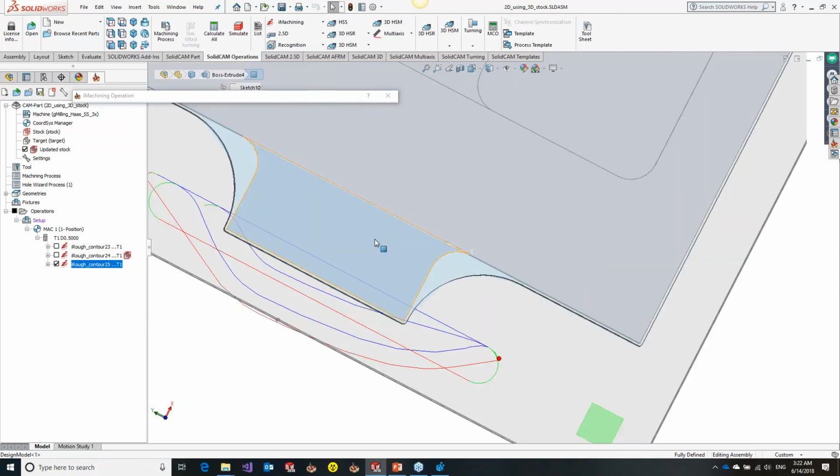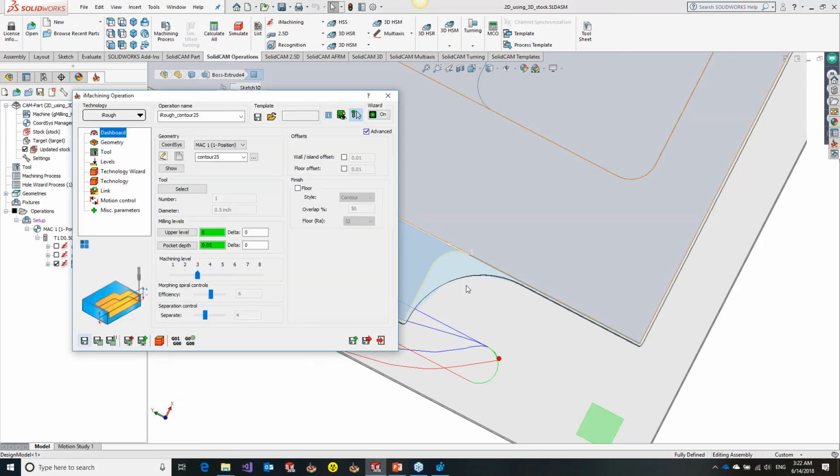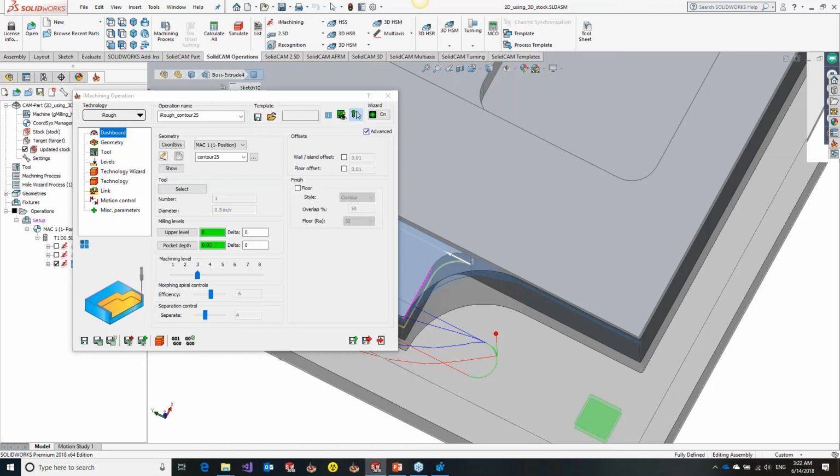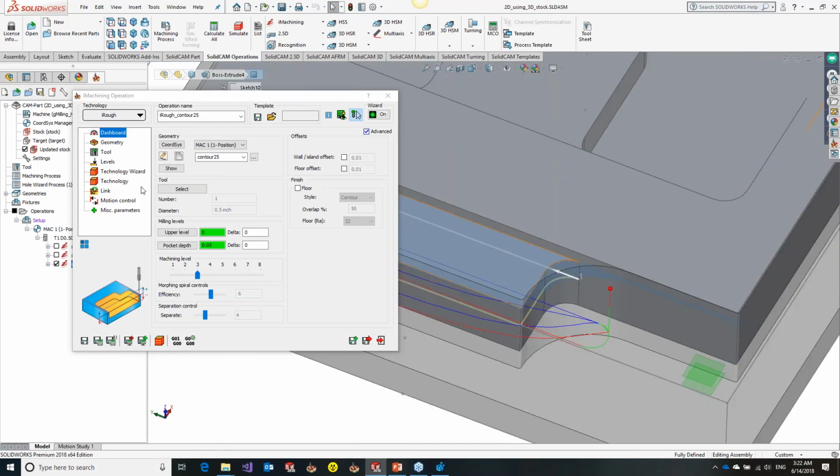In typical iMachining, if we had just selected this face, the tool would have plunged into material, kind of like the same thing I had shown in the multi-tool operation with open edge offset. But in this case, you start to get more complex situations. So now the user doesn't have to know about the stock, doesn't have to set open edge offsetting, doesn't have to worry about it. We take care of all the geometry extension and everything automatically.